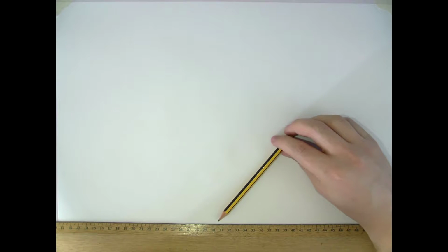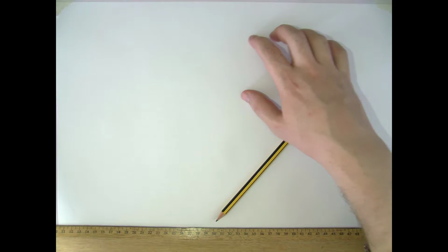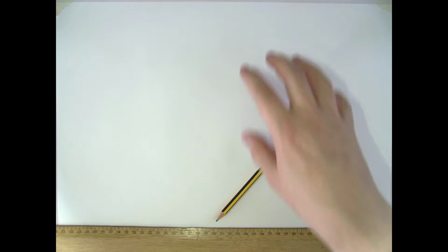In our plan, surface A is going to be something like this. It's going to be inclined at an angle of 30 degrees, so we need to look in perpendicular to that. For this reason, we need space either up above it, top left, or down bottom right. So when we're positioning our question on our page, it's important to take that into account. I'm going to put the elevation up here, top right, plan, bottom right. My auxiliary elevation is going to go top left then.